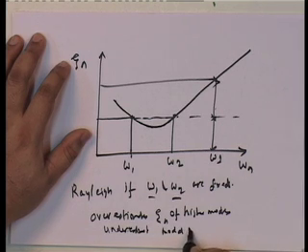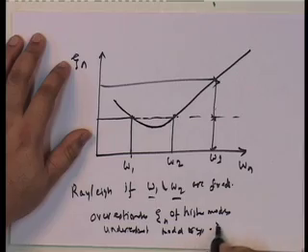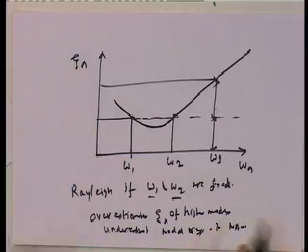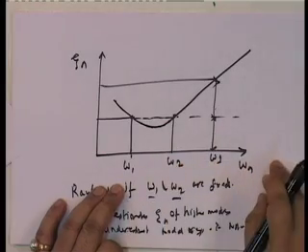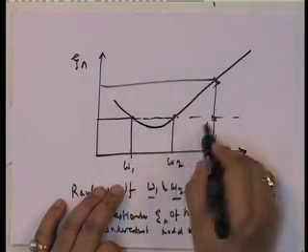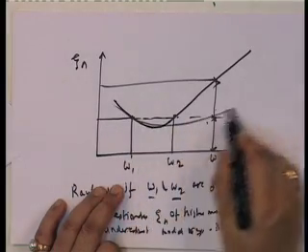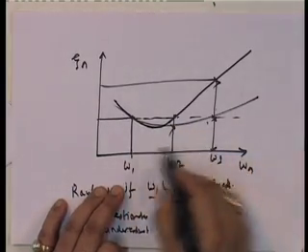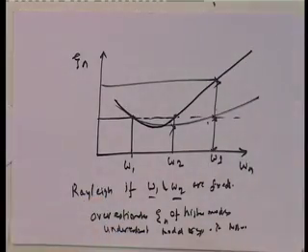modal response in higher modes. So, in other words, in this process, what are we doing? If we do this, now there is another option. The other option is instead of omega 2, you do some other omega n. But then what happens is, if you fix this and you fix this, all that happens is that it underestimates the middle ones and overestimates the higher ones.